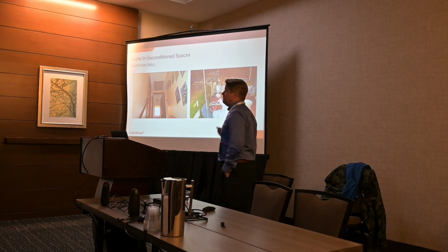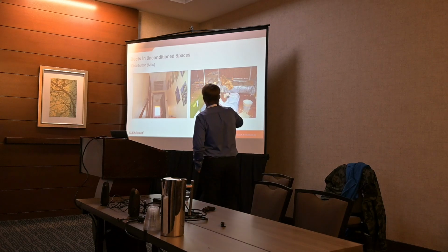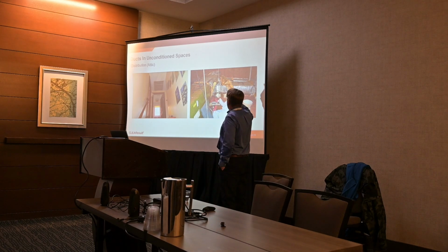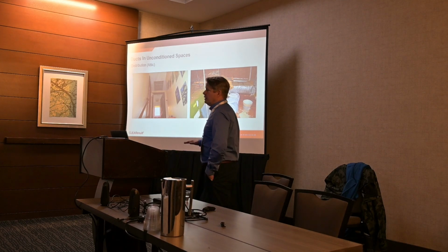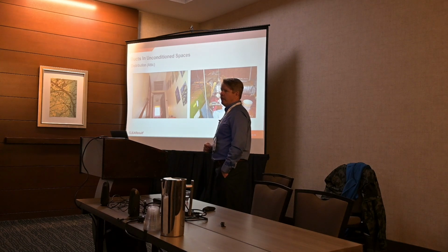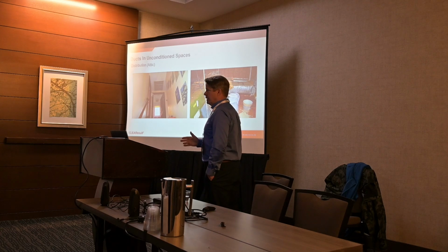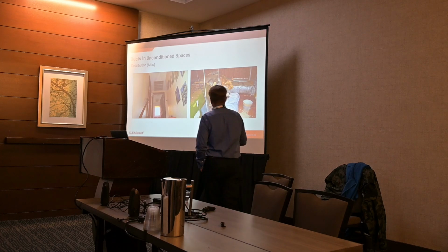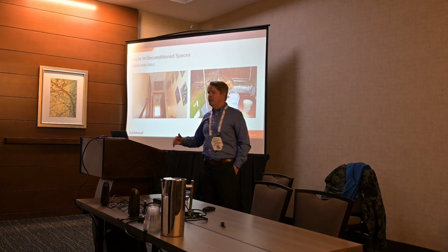What's code in an attic? R8, okay? The International Energy Conservation Code's attic insulation on ducts should be R8, and the other space it's R6. Do you have to stop at code? You don't, right? The code is the worst house you're legally allowed to build, okay? That's what code means. You can do better than code, it's okay. If this system is down on the floor, we can blow insulation right over it and push it right inside, right?